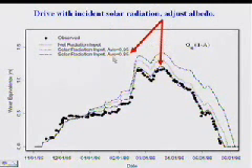Then we had one of the albedo parameters, and we drove the model with measured incoming shortwave radiation rather than the net radiation. So now the albedo calculations of the model are actually active, because if you're driving the model with net radiation, it's bypassing the albedo calculations. And we found that by adjusting the one parameter from 0.95 to 0.85, we were able to move from that line to this line down here and get a fairly good match to the observations.